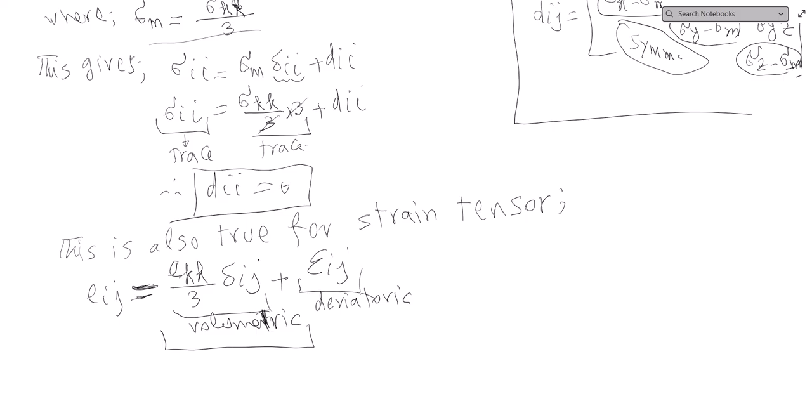Basically, this part of the strain is responsible for changing the size, expanding or contracting a stress element. But this part is responsible for changing the shape. This changes the size, shall we say, but this changes the shape. And this is the part that we are interested in.